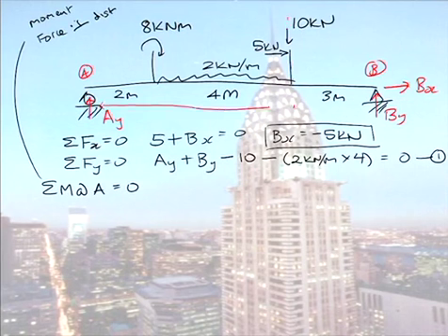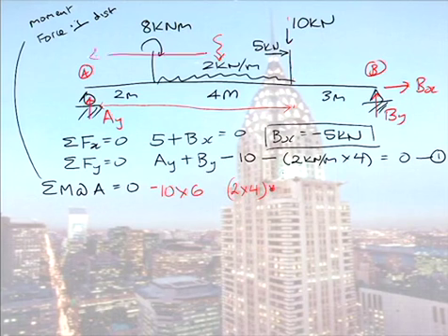So everyone, I think, in this room knows when we look at the moment caused by the 10 force, it's 10 times 6 metres. It causes clockwise, the way it's drawn. It's rotating clockwise about A, so it's negative. My UDL load, 2 times 4. When we assume an equivalent UDL load for a linear loading, we put it in the middle. So that distance would be 2 plus 2, times 4 metres. That's also negative. But in this instance here, we also have a moment applied, and a moment is a moment. We have a moment of 8.